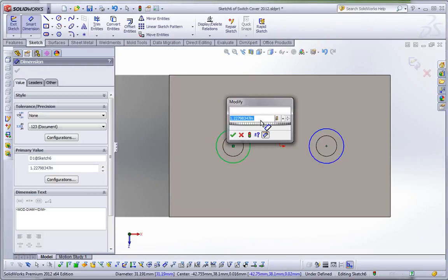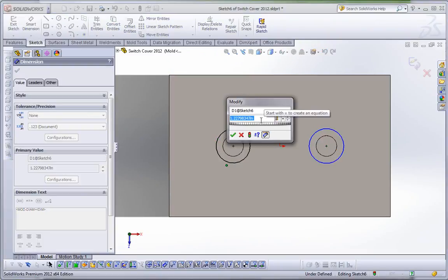And the value in doing this is that it always gives you the same offset, regardless of how the size is. And obviously, there's other ways that you could do this with a dimension, but if you use move face, regardless of how or what size it is, it's always going to be offset the amount that you specify.